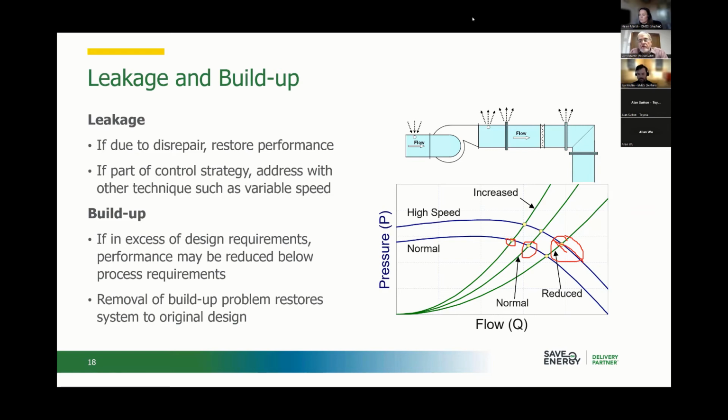But I went in there and took a look at this fan, and this poor little fan, I don't know why it was still hung together, because it was supposed to be about 1,800 RPM, and this guy had it running at about 5,000 RPM. I'm amazed that he had enough motor that he could run the thing. But I ended up taking a pressure across the fan, just like I've advised at a few different points: know what your system is and get the pressure. Right across the fan, we had 20 inches water gauge. I'm looking at this thing going, what's going on here? You're not moving any air, but you've got 20 inches water gauge.